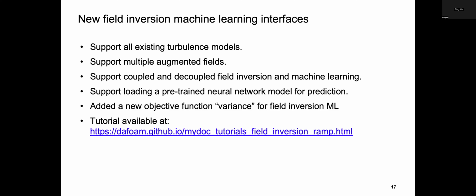But if you are thinking of more complex cases, we haven't really tested a lot, because I assume most of the users use DAFoam for incompressible flow or subsonic flows. For transonic flows, sometimes I agree that it's not as robust as, for example, ADflow. In this case, maybe ADflow is a better choice for transonic or supersonic flow. That doesn't mean it cannot handle transonic flow. It can handle simple transonic flow. If you're thinking of a very complex case, it definitely cannot handle supersonic flows. But if your Mach number for an airfoil is like 0.7, 0.8-ish, maybe it can do okay.